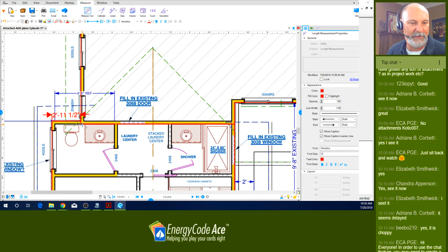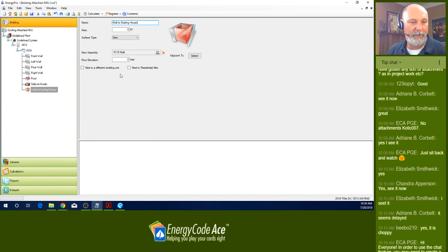I'm going to take a dimension here. I'm thinking that if we subtract it, it's 15 foot 10 there. So we'll call that 15.8333 times 9. Let's call it round numbers, 143 square feet. So we'll come back to EnergyPro and call this area 143 square feet.